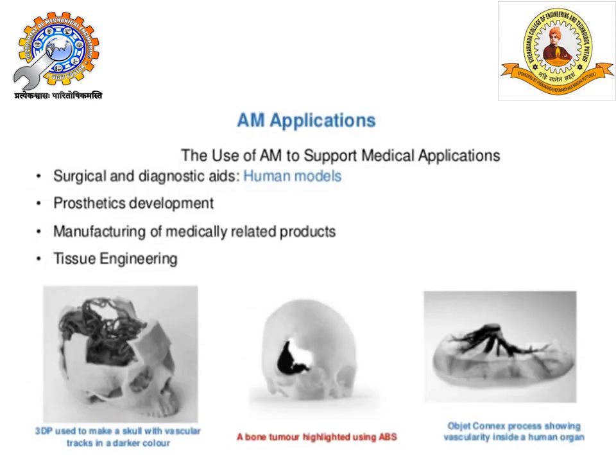Step 2, conversion to STL. The term STL was derived from stereolithography, which I'm going to explain in my next session. STL is a simple way of describing a CAD model in terms of its geometry. It works by removing any construction data, modeling history, etc., approximating the surface of the model with a series of triangular facets.